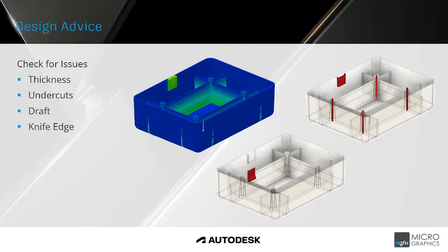And then lastly, knife edge. We don't have any knife edge images shown here, but this would highlight any sharp edges that could potentially break off in the mold when the part is demolded. So potentially at the top of these ribs, if they came to a sharp point, that would be highlighted as a knife edge.